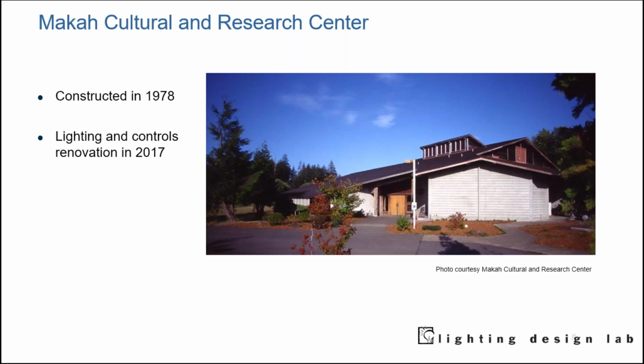Because the fan coil units no longer worked and the cases were never designed to be turned off, once again because of those fan coil units, the lights stayed on 24/7 for years. The conservator had to reduce the light levels on the artifacts to extremely low levels, which made that incandescent light even warmer, to a point where details of the artifacts were hard to see. And in some cases, lamps were too close to some objects, and the paraffin treatment began to dry out from the heat of the lamps.